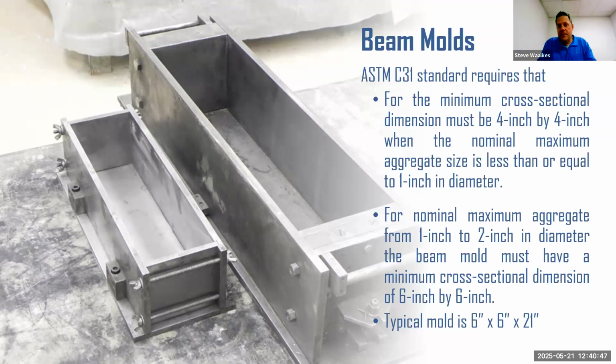And the spec is that the beam itself has to be 1 inch longer than the center line of those supports below it. So 20 inches technically, if we could be perfectly to the right length, but most of them add an extra inch. So a 6 by 6 in cross section, and then 21 inches long is the concrete beam, the inside dimensions essentially of the beam mold. That's what's most common.